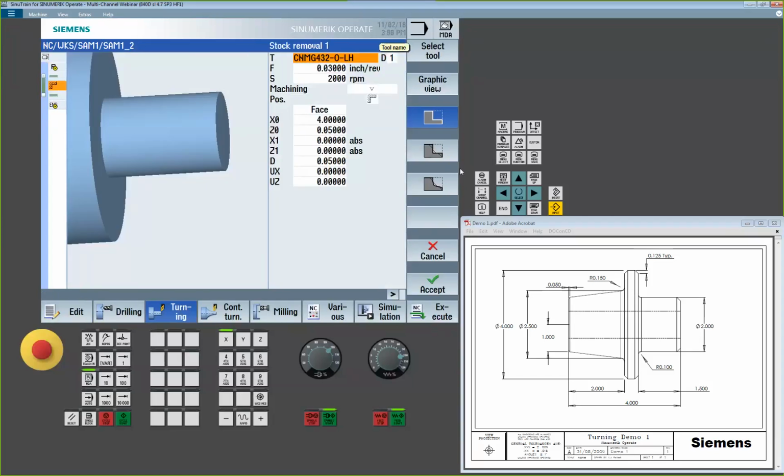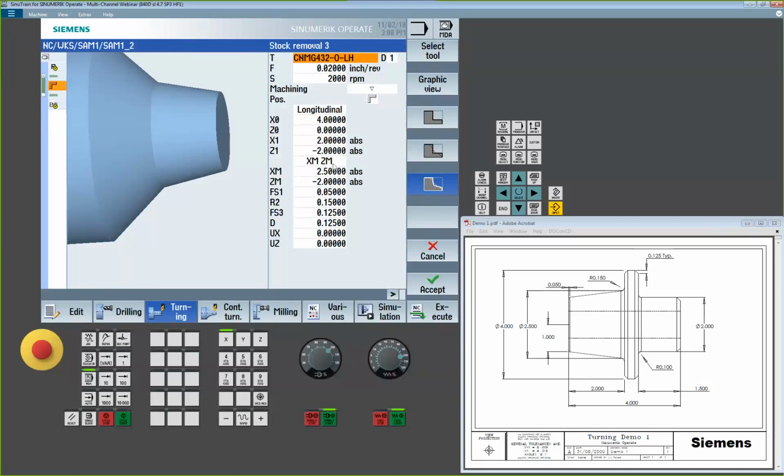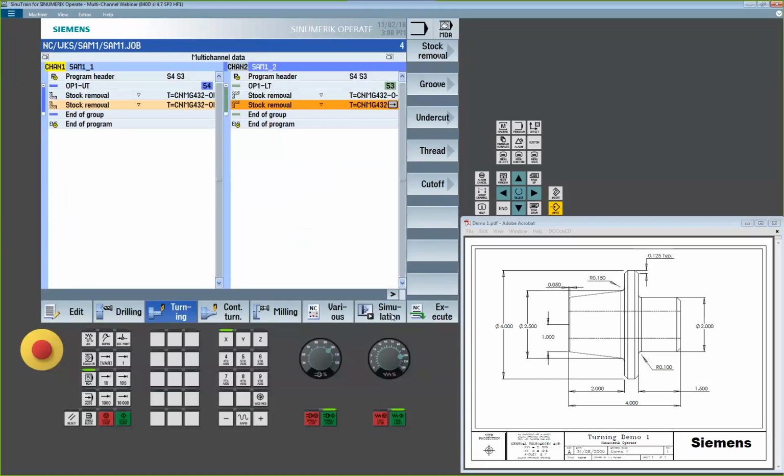So I did this one with the tapered tool. That's how I'm getting that taper in, a couple of those fillets, right? Okay. So we got some toolpath in. So let's simulate it and let's see what it's going to look like.